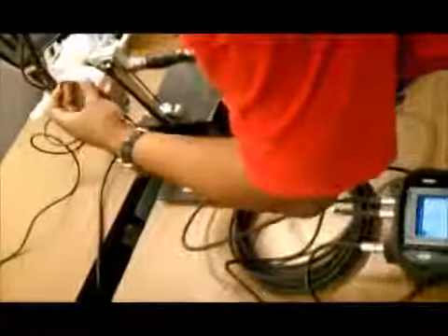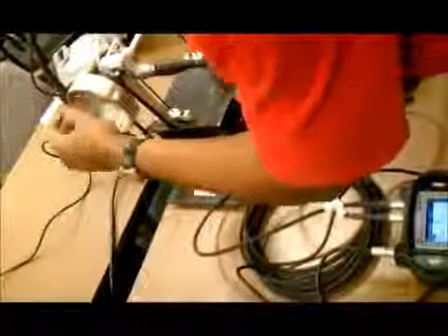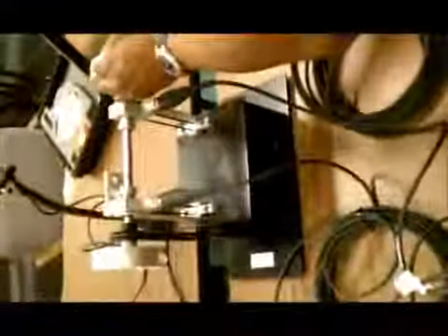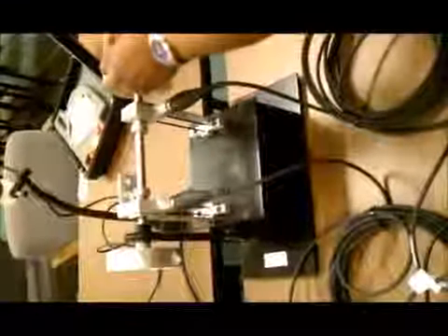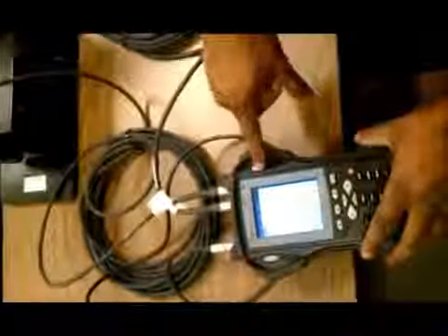So what we want to see is a change in our mils reading, which we have, because it's going from 2 something to 10 something, which means we've had more than our 30% change. So we'll hit our fire key to capture the reading, and it's going to ask us if we want to keep the trial weight attached or no. In this instance, we're not going to keep it attached because it's easy to remove. And we're going to put it on our second plane. So once again, we'll line it up with our 0 point and start it up and press our fire key.